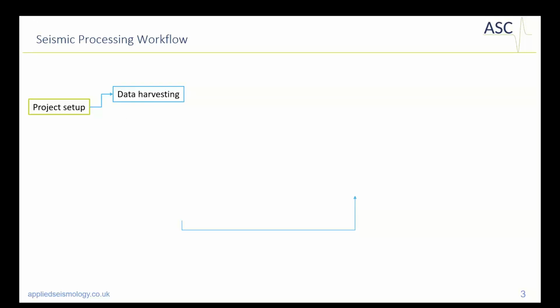Specific to this application is the extraction of data from the acoustic stream. Importing the data that has been extracted if we are working on a trigger system. And the conditioning of our waveforms, they require some pre-processing. Basically, the removal of the DC, some filtering, some cleaning up of the signal so that it can be used for further interpretation.